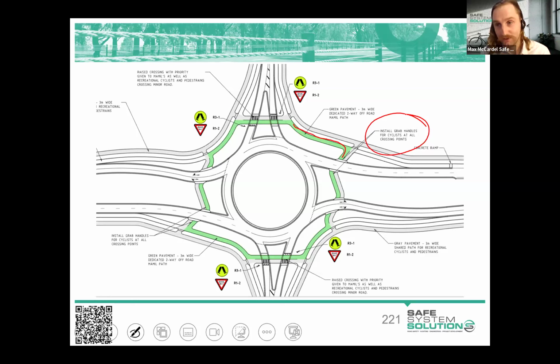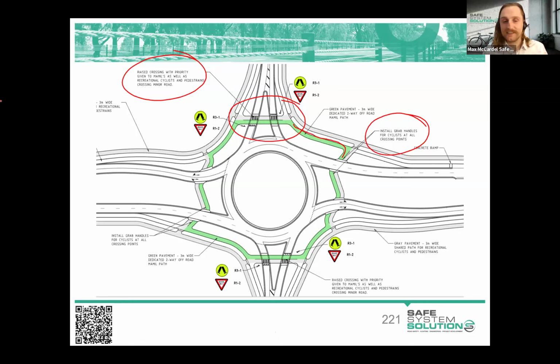Vulnerable road users need to stop and give way. If I compare that to what it's like crossing over the less important movement corridor, once again, we'll have a look at what the designer has said, and they're saying, let's install a raised crossing point so that we can actually award the priority to cyclists and to pedestrians. So it's just a demonstration that you can have different treatment selections dependent on what those movement functions are for your road environments.